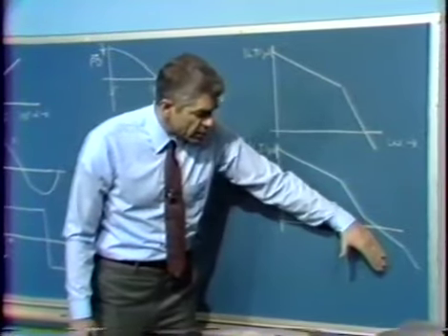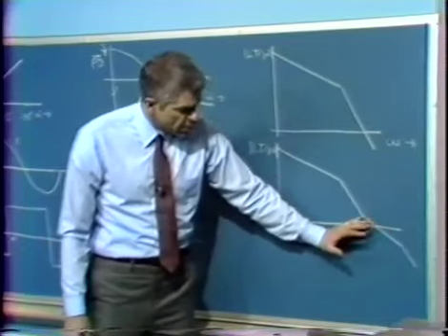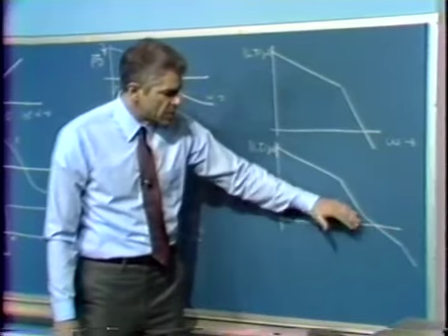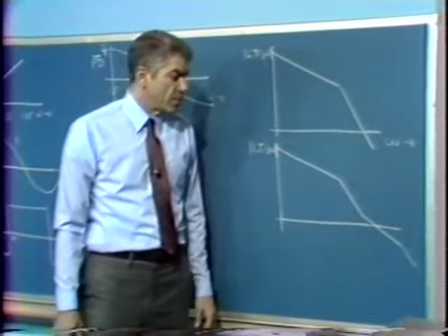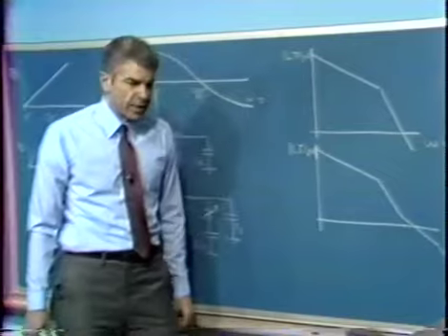that correspond to either crossing over with a 1 over s squared kind of a roll-off, where we pushed out the zero to higher frequencies, or we can cross over with a 1 over s kind of roll-off that presumably should give us considerably better stability.